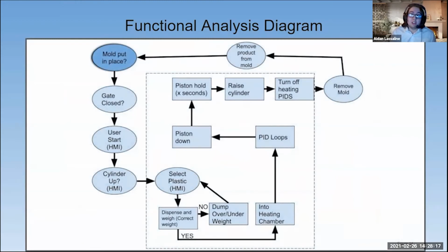Our injection molding machine operation begins with the operator closing the safety gate located on the front of our machine. This safety gate needs to be closed because it prevents the operator from coming in contact with the heating element, and pneumatics will not function unless the door is closed to ensure the operator does not have a hand in the piston while it is pressurized.